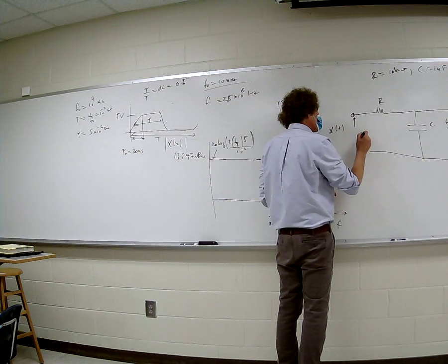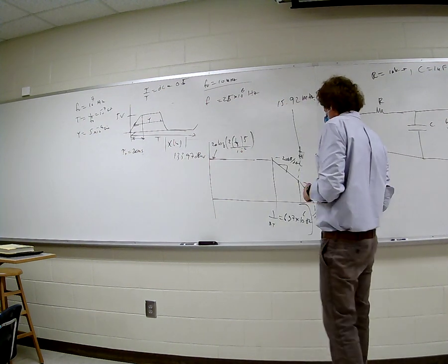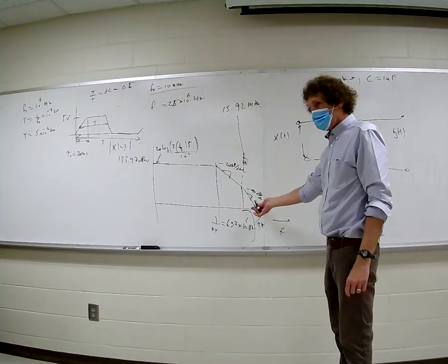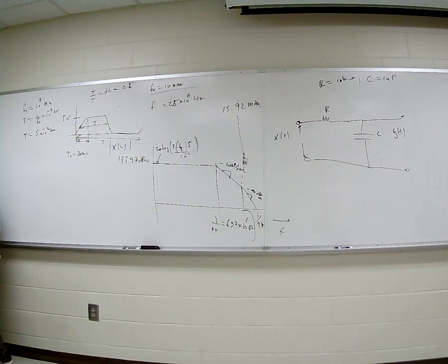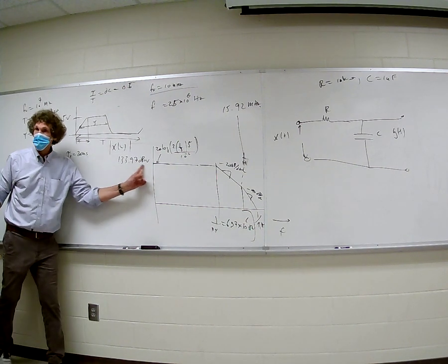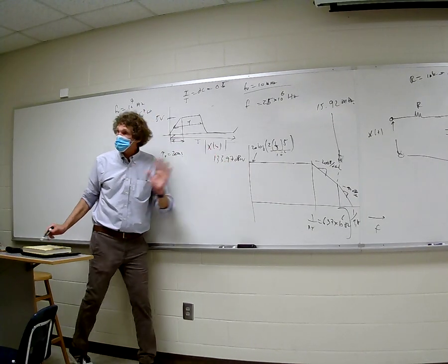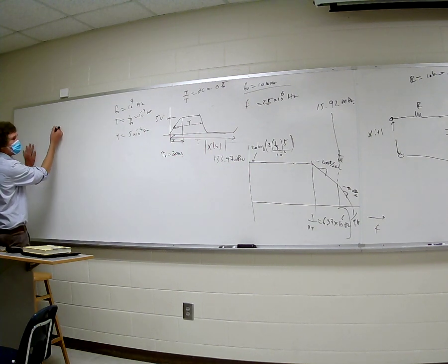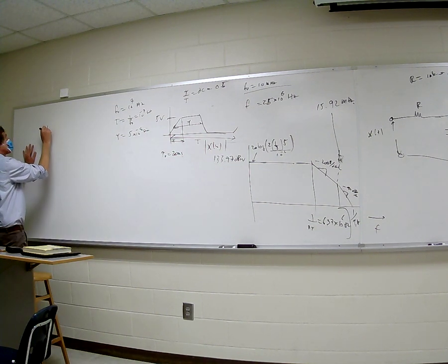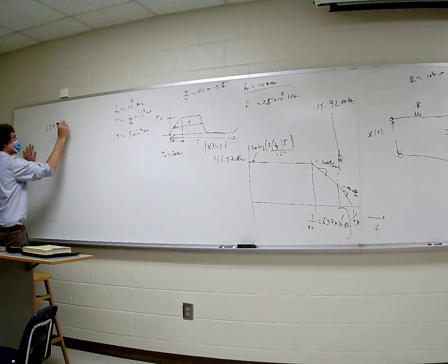at that frequency right here. Right there. And the way I do it, I bet a lot of you know what I am going to do. Okay, I'm going to start here, right? Agree? This is just the input, not the filter itself. You agree, class? So I start there, and what is that, 133.9? So call it 134. 134 dB microvolts, right?